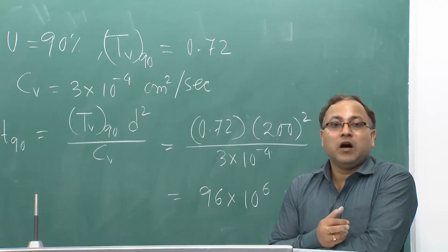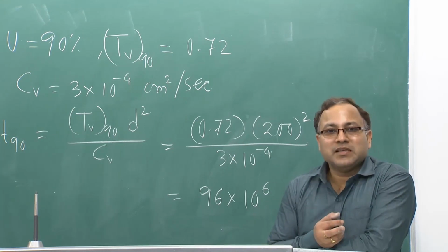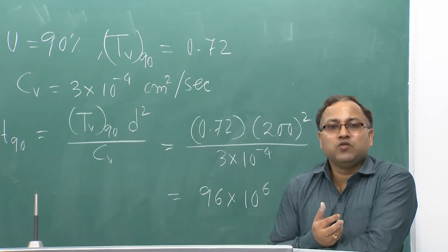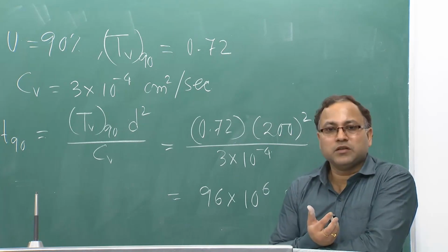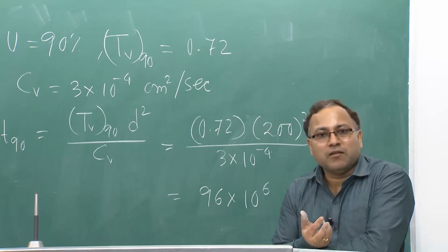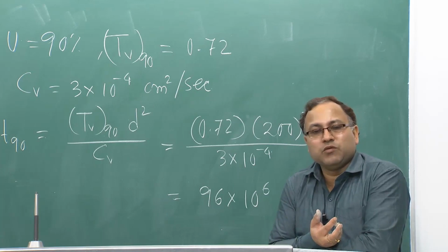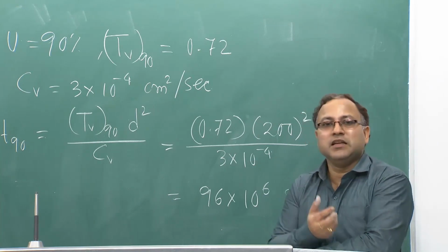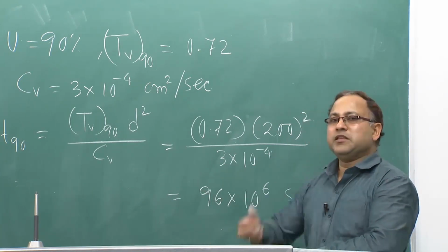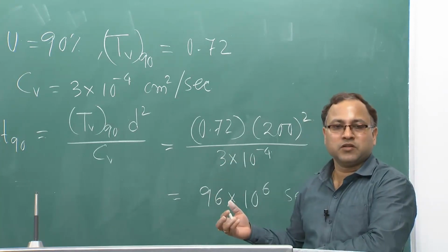If you want to accelerate this process, you have to facilitate the drainage, otherwise you do not have any other control, right. You cannot change the deposit that nature has given, unless you do some modifications like excavating the whole soil and filling up different soil.